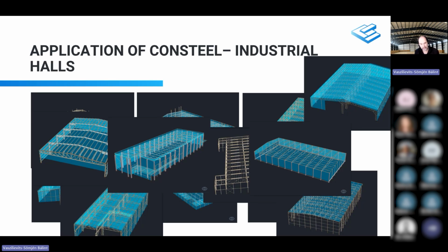Their buckling length is equal to the floor height, which is something like 3-4 meters. If you have a decent size of H profile, buckling doesn't play any important role to be checked. The floor beams are all supporting the concrete floor. Top flange is continuously stabilized laterally by the concrete or by the trapezoid deck what is connected to. Therefore, there is really no very high need to make stability verification.